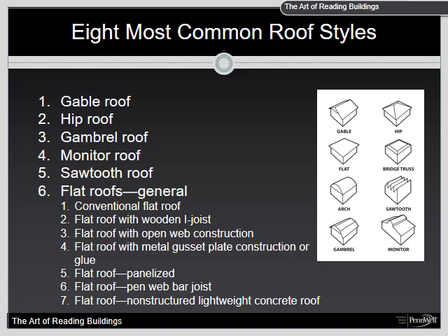Additionally, as warm interior air rises, the windows can be used for interior ventilation if they can be opened. This roof is commonly constructed with rafters of 2 by 8 inch or larger and can use wood and or metal support for bracing. The sloping portion is characteristically covered with 1 by 6 inch sheeting and composite roofing material. This type of roof is constructed basically the same today as it was in the 30s and 40s, with the exception of the sheeting. Numerous support posts are required with the sawtooth design, increasing the strength of this roof as compared with a comparable flat roof with larger open areas.